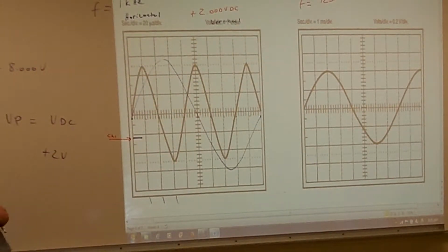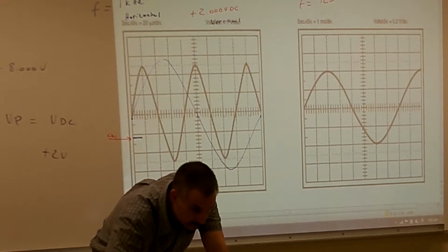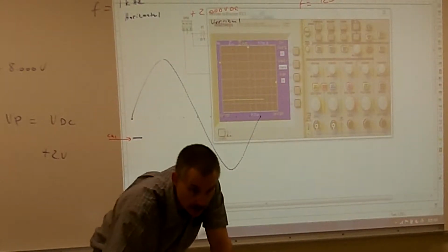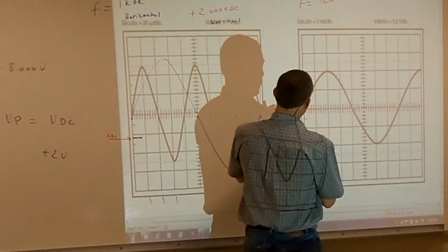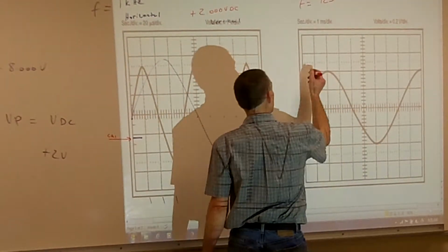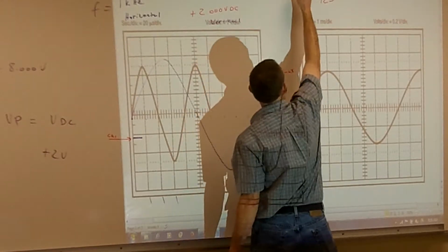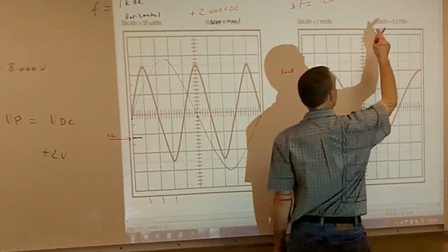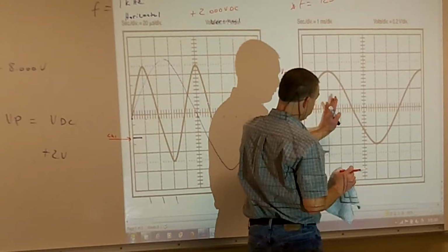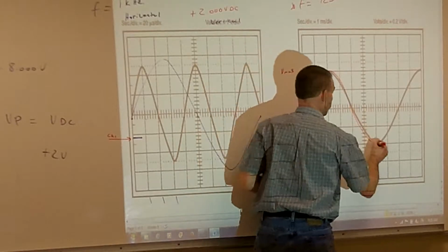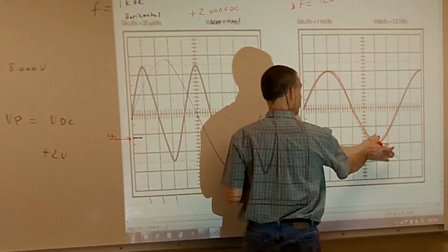Now, one thing nice about the digital scope is that we can go to our measure button on the oscilloscope. I can even bring it up and show you what we got. On my measured one, it'll tell me what my Vmax is, my Vmin, my period, my frequency, my voltage peak, and my peak to peak. So I can have it display everything on here. It works very well for very basic sine waves and square waves, as long as the waveform is basic.